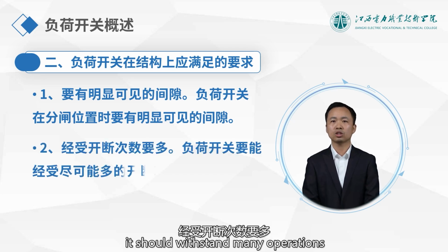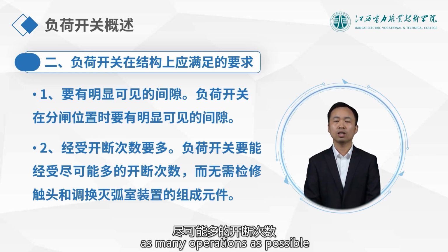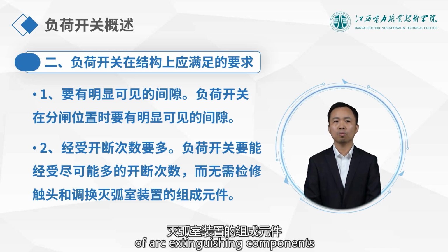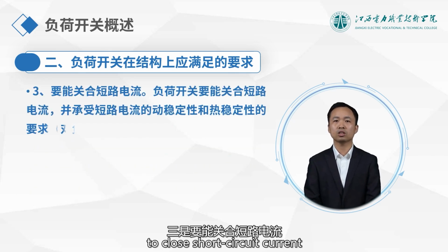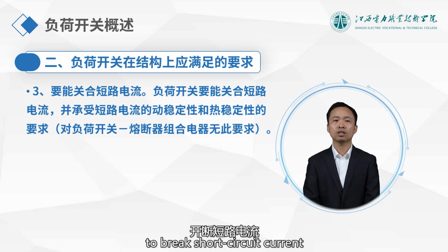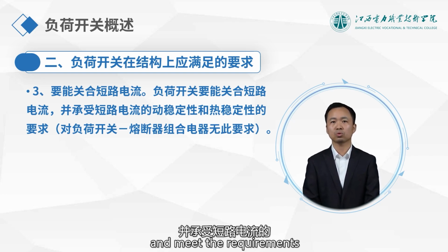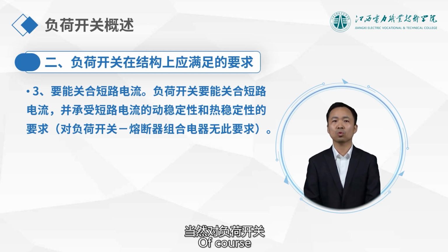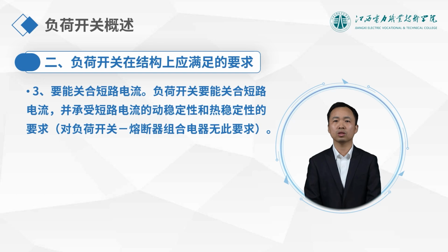Second, it should withstand many operations. The load switch should endure as many operations as possible without requiring contact maintenance and replacement of arc extinguishing components. Third, it should be able to close short-circuit current. The load switch is not required to break short-circuit current, but it should be able to close short-circuit current and meet the requirements of dynamic and thermal stability. Of course, this requirement does not apply to load switch fuse combination switchgear.